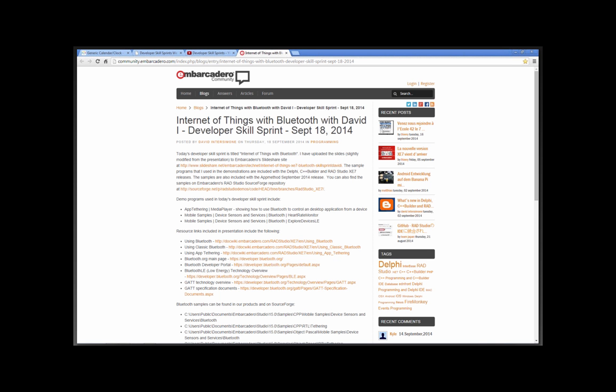Let's see. If I have 25 heart rate monitors around me, they would have 25 different GUIDs. Well, no. If they're GATT standard, they'll have a common GUID, whatever it was, 180D in the first part. Then inside of that, once you find them, you can look at information about each of the heart rate monitors. They each will have the manufacturer name. They'll have probably a serial number, a version number of the device, like Wahoo Scale. The manufacturer was Wahoo Fitness. The version number was 1.3.